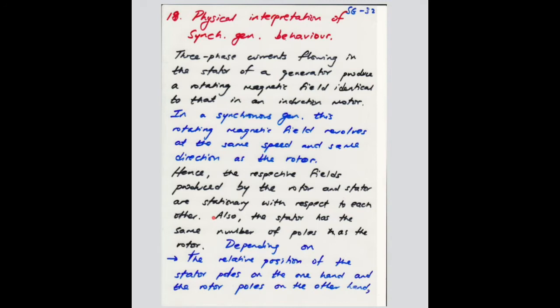Right. So if we go back to the basics, as we know, the three-phase currents flowing in the stator of a machine, same as in your induction machine, produce a rotating magnetic field, right? The speed of this rotating magnetic field is your synchronous frequency, right? And in a synchronous generator, the rotating magnetic field rotates at the same speed and direction as the rotor,